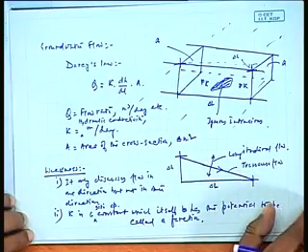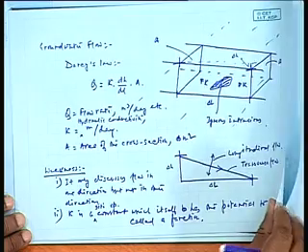To understand k as a constant over a length of aquifer, say about 2 kilometers, 3 kilometers, 4 kilometers, is too simplistic. K itself cannot be a constant. So k can be a function by itself. The nature of the functions can change depending on the construction of the materials in the aquifer, isn't it? But then again, whatever weaknesses we say, this is quite popularly used.